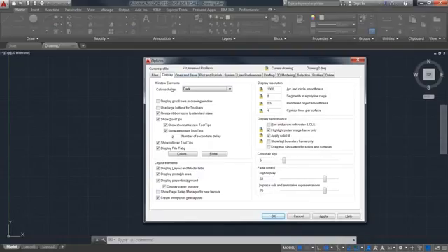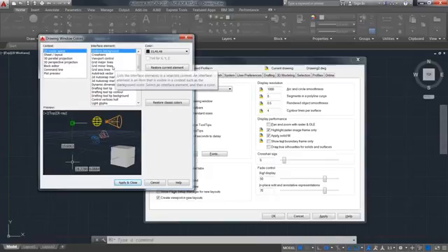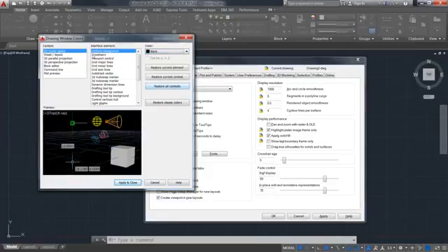So what I wanted to cover first is the display tab. There's a couple of color schemes that we ship with. Makes it so that the buttons in the ribbon are darker or lighter. But where a lot of people like to go first off is into the colors area down here. And within colors, you can change virtually everything about the way AutoCAD looks and feels, from the background color, which you can see is kind of a dark slate gray. You could just make your uniform background straight up black, which a lot of people like because that's the way the older programs made it.